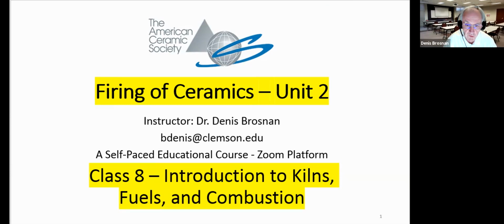So this is a very practical aspect of the course, and we've been through a number of lectures on firing ceramics, what happens inside of the ceramic, the reactions and transformations that happen in firing and sintering have certain demands for energy. Certainly, they are thermally activated processes.